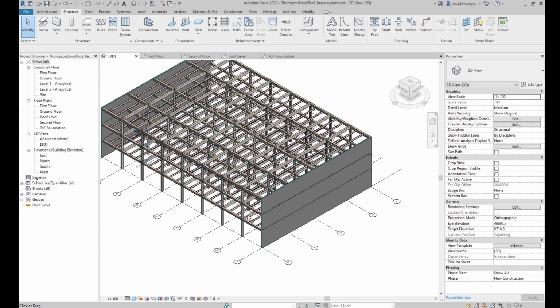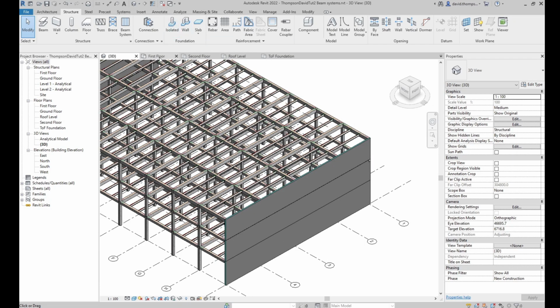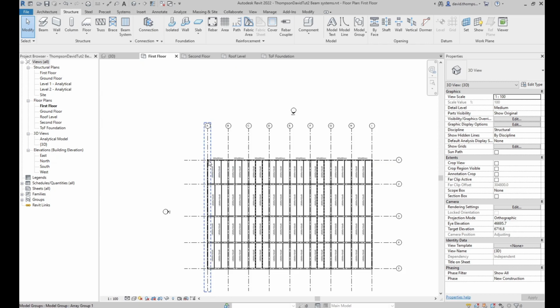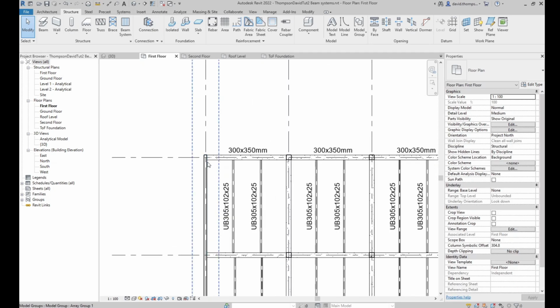And again, if you haven't done it before, it's always good to double check that all our walls are connected. So just make sure we join the walls at the outer edge of the beams, like we did earlier on. It's no harm to double check your floor plans, make sure that the walls are going where they should. I think we did them already, but before we move on, just make sure that the walls are going out to the end of your beams.